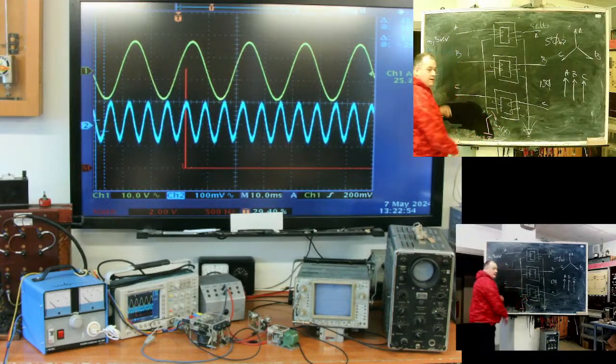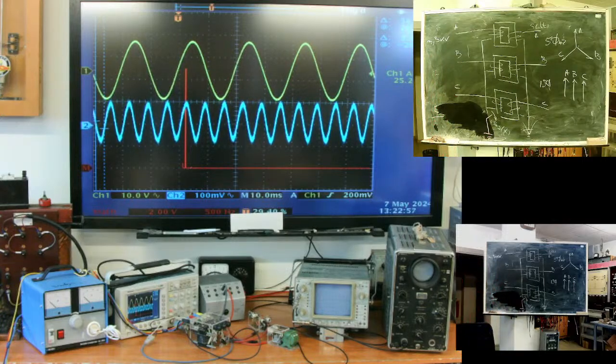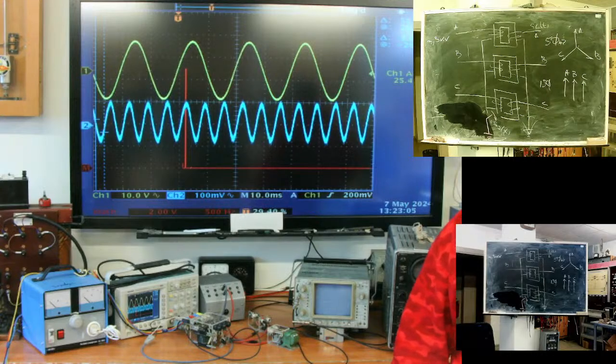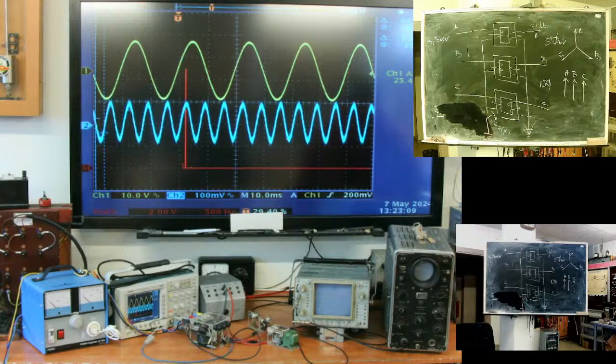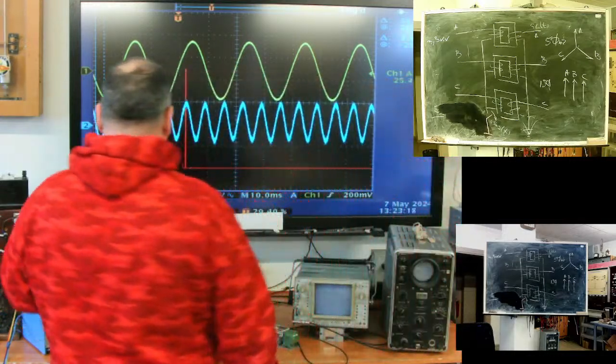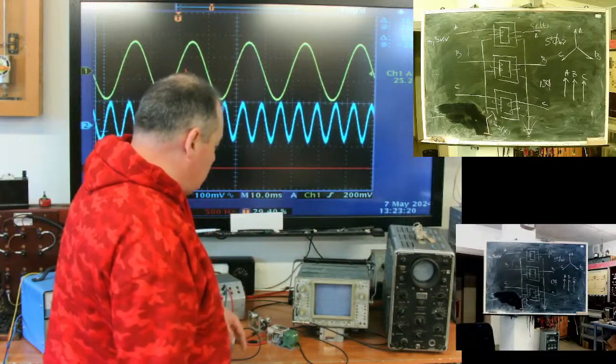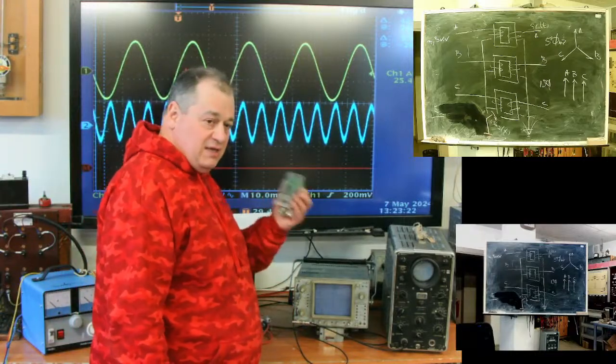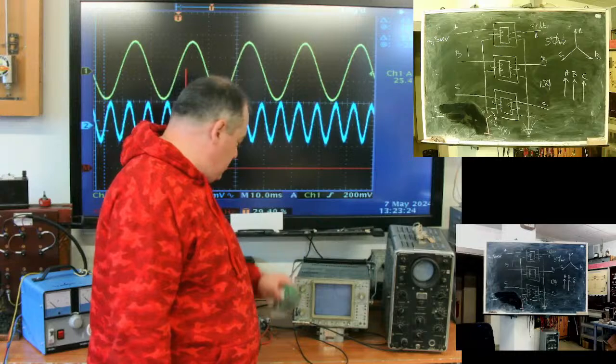What will happen if I disconnect the switch, only on the earthing side? If we have a symmetrical load, for 50 Hz it changes nothing, because the sum is 0 anyway. But for 150, it can no longer flow. We will see in reality the same situation, the same idea that I artificially created with the circuit.